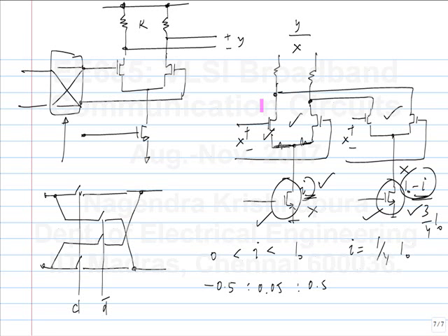So if you had a single differential pair where the tail current was varying, then as the current becomes very small, the linearity really goes to pieces. Whereas in this particular case, when this current is small, the other current is large, so the linearity is not too bad.